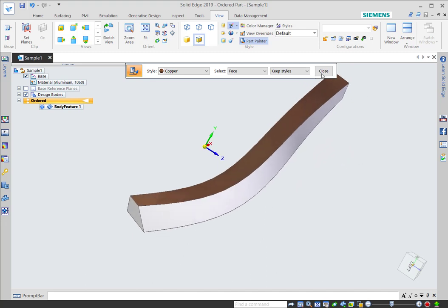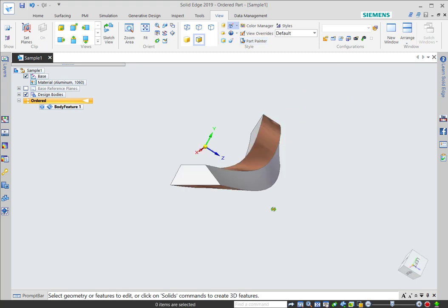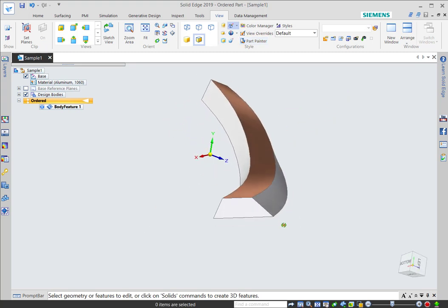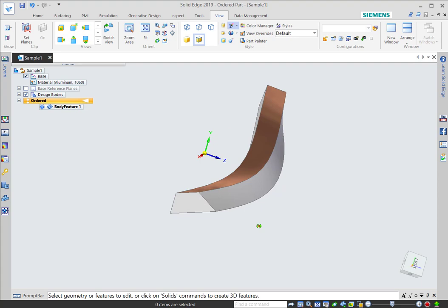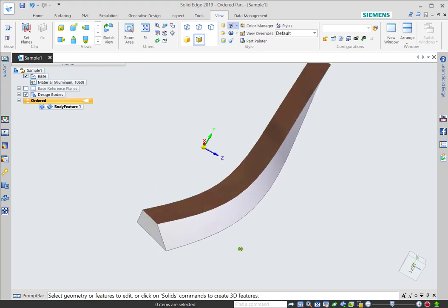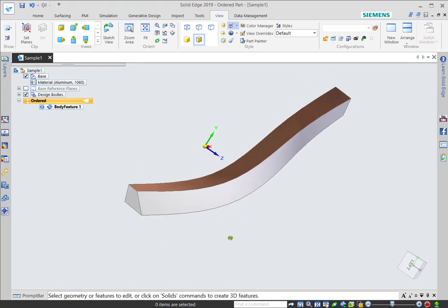that this is going to be manufactured from. It does have bevels on the edges so we'd like to cut this out with probably a CNC router and then be able to just kind of twist it because it's a flexible foam type core material, and then it will fit into the shape. So what is the shape of that flat piece of material?